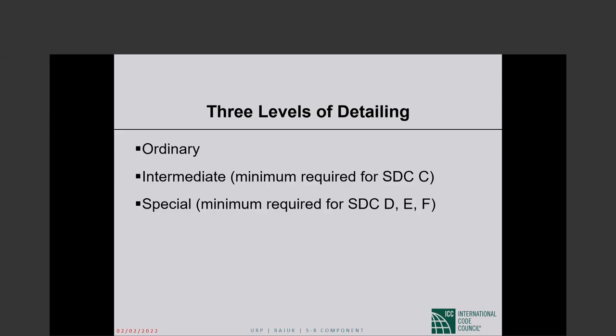In other words, at least theoretically, seismic design is an exercise in trade-off between strength and inelastic deformation capacity. The higher the strength, the lower the need for inelastic deformation capacity. The lower the strength, the higher the need for inelastic deformation capacity. In reality, our codes do not allow us an unrestricted trade-off between strength and inelastic deformability.